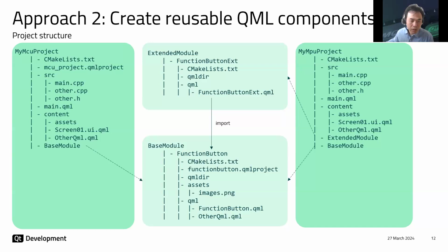In the Figma bridge, you have the option to disable the advanced features that are only available for MPU, and you can export for either MPU or MCU projects. Later you can use the generated QML files as the base of the UI design. If I did that, I would definitely not use it directly in the real project, but use it as the basic view and then optimize it in the QML file.